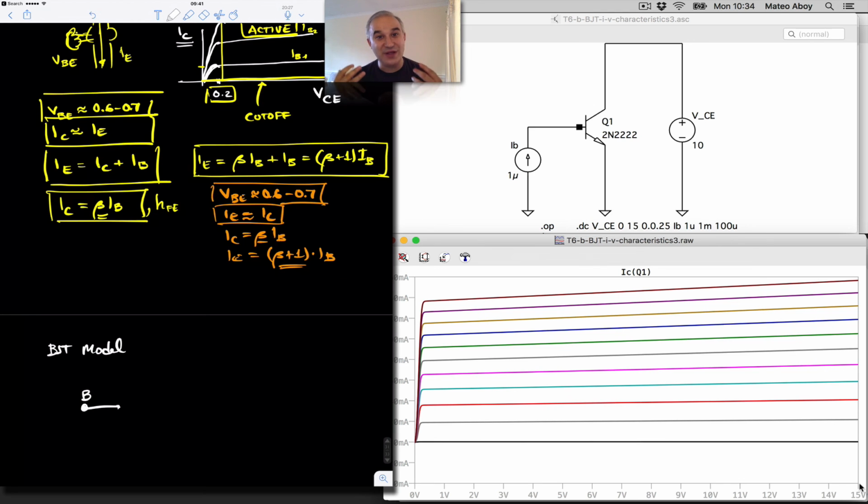That's it. That's what we can do circuit analysis with. So if you get a new device, a new structure, NPN structure, well, we need to model it with an equivalent circuit. Now, models have different complexity, so the simplest model that we could think is, okay, this is going to be a diode, for which we already have a model as a voltage source between the base and the emitter.